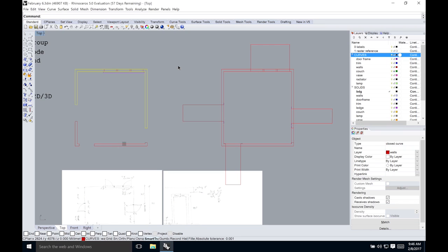Except I would say that it's worth keeping everything that you work with during modeling, because first of all, if you discover a mistake later on, then it's quite possible that that mistake comes from the base geometry. So let's say you created an extrusion, but your curve wasn't closed, so it wasn't a continuous loop, and so that extrusion is just an open surface, and you might want to just go back to your curve, close it, and then extrude it again instead of trying to fix a 3D geometry, which can be harder.